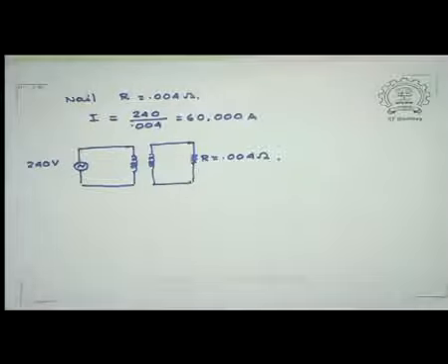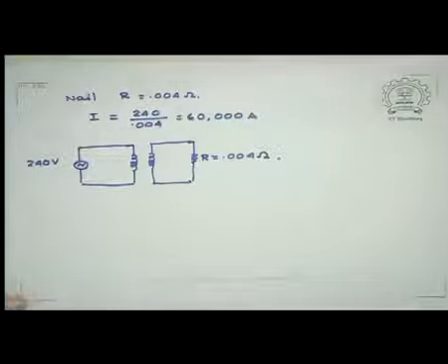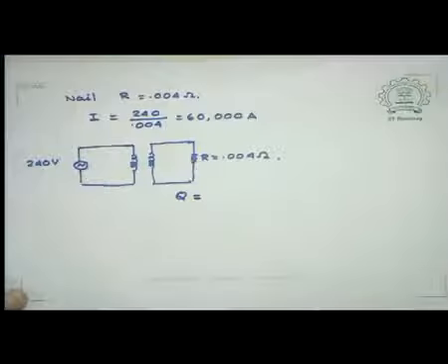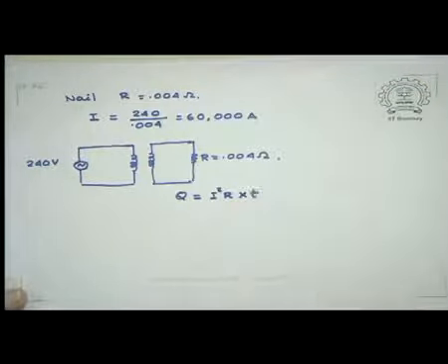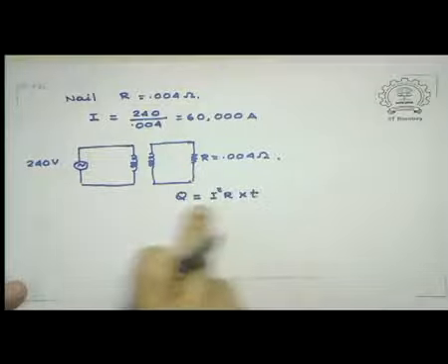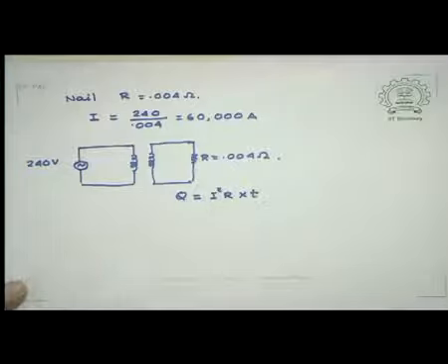Now the way to do it is the following. I calculate using properties of this piece of nail, like its mass, its specific heat, etc., and find out how much heat I need to melt this over a certain period of time. Now suppose I did that calculation, then my Q, the amount of heat that is required, is given by I square R times the time, which, let me take it to be a couple of minutes for convenience, and I can easily calculate how much current I require, because everything else is known to me.